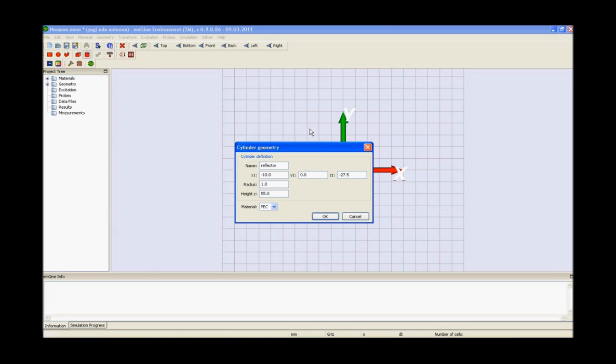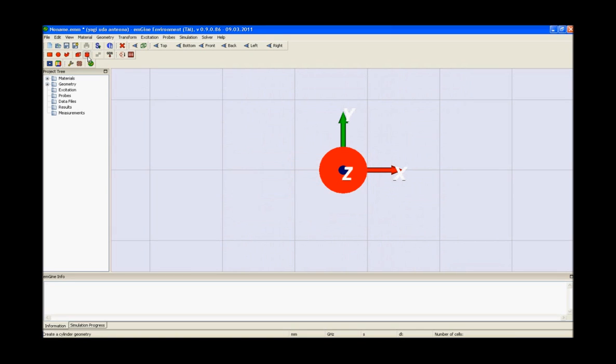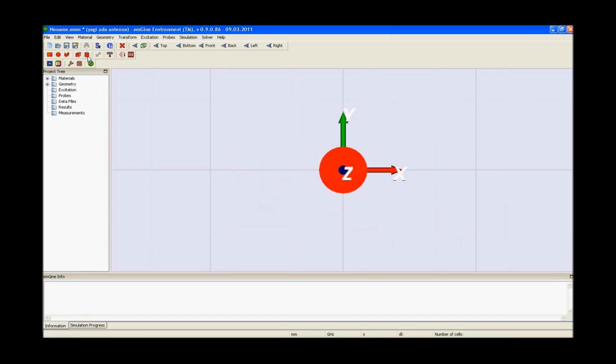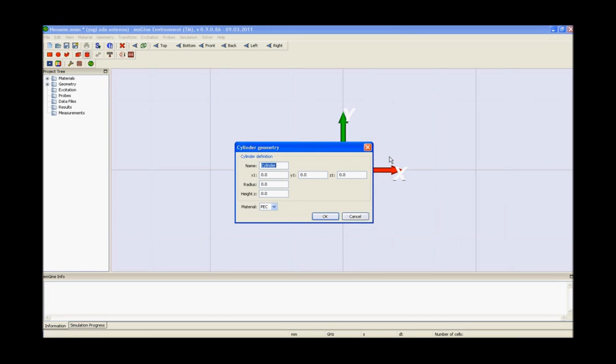After creating a reflector, we need to design a director of cylinder for modeling of wire-type Yagi Uda antenna. For this, we again need to create a cylinder made up of PEC material and entering the transversal coordinates. Once we've done this, we need to create two more directors, and hence we need to repeat this process 2 more times.